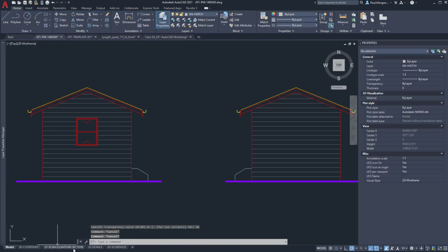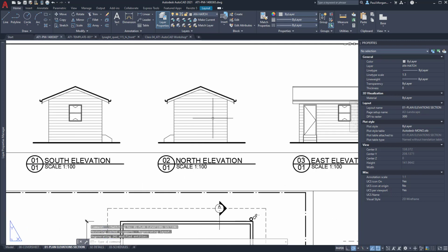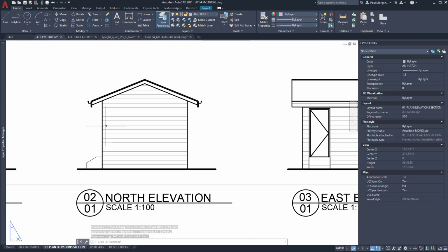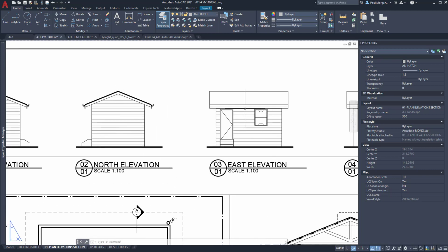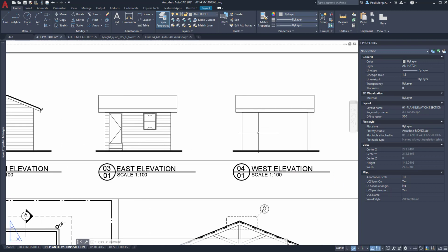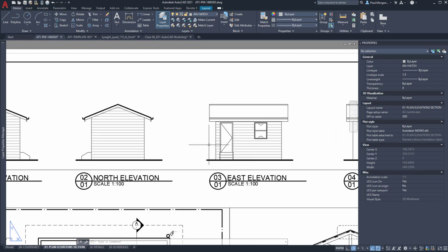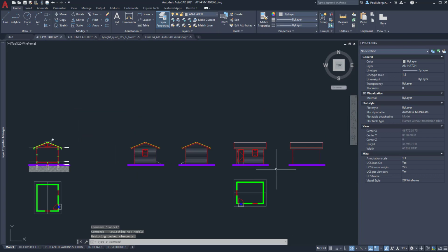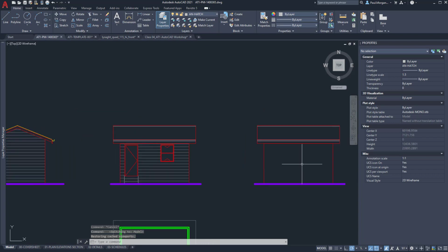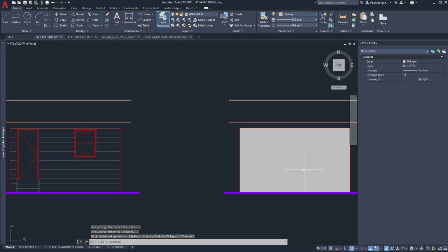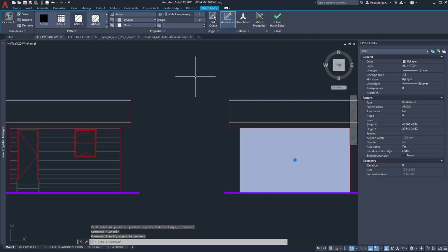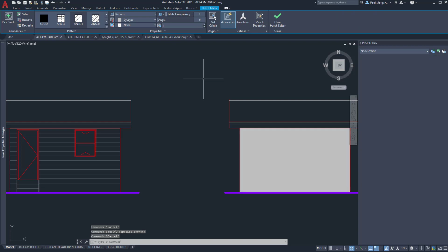That looks really good. And even if I go back to my drawings here, you can see how that's coming up. And again, because you're using that lighter color, it just is not so overbearing. You can clearly see the shape of your building, and then the pattern is just sort of complementary. Okay, but notice that we didn't hatch that last one. So as we were editing them, we were editing all of these at the same time. The problem is that because now I haven't done this one, I can't just add a hatch. I have to go and do that same command again, bring it up, go to here, hit escape, click on it, and then do that same editing all over again. It's probably not the best way to do it.